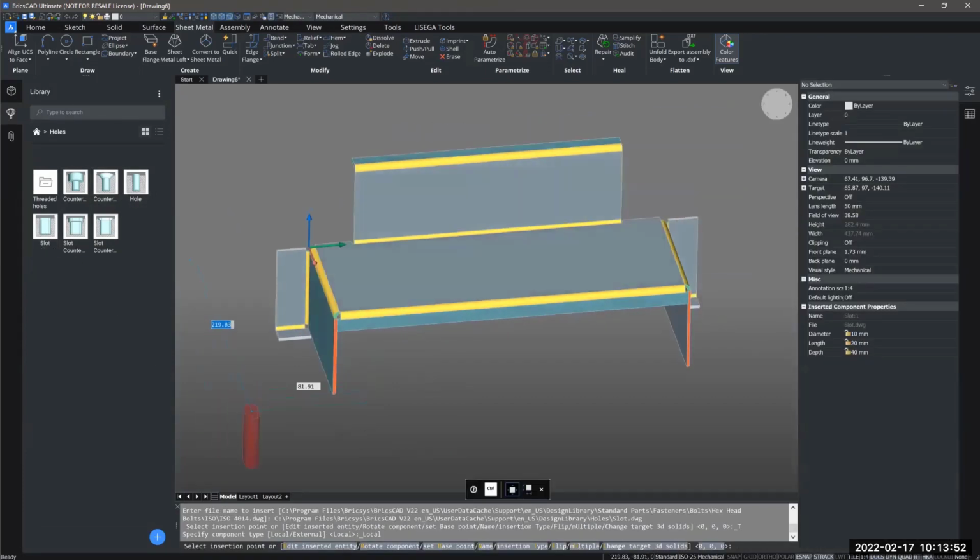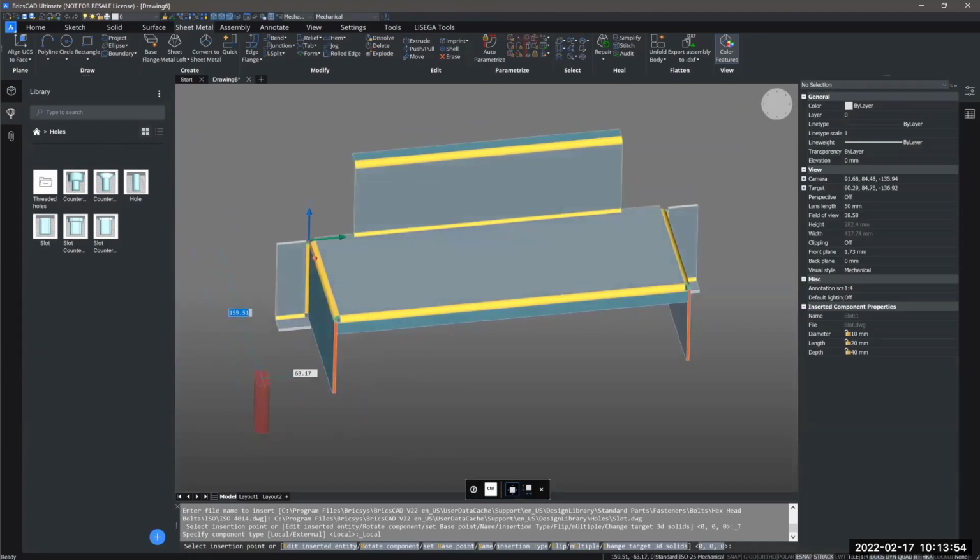And you will remember from the parametric components exercise that we had the holes that had the unite layer and the subtract layer. These holes work with the subtract layer and will allow you to place these to remove material from what you place it on. These are also fully parametric, so you can change the parameters after placement or before placement.